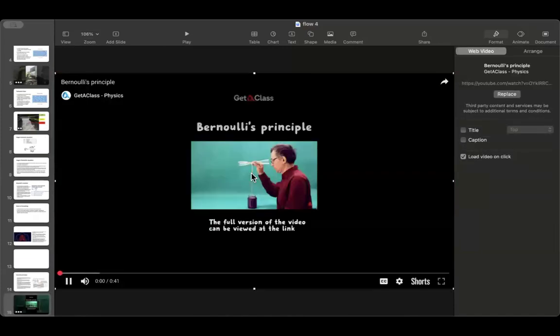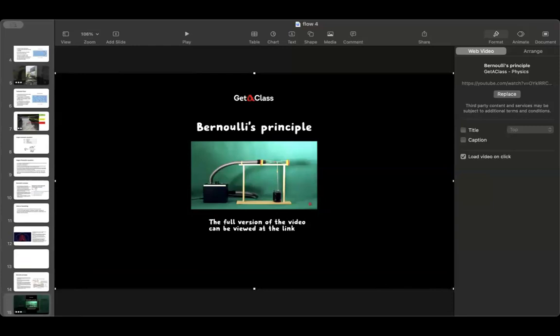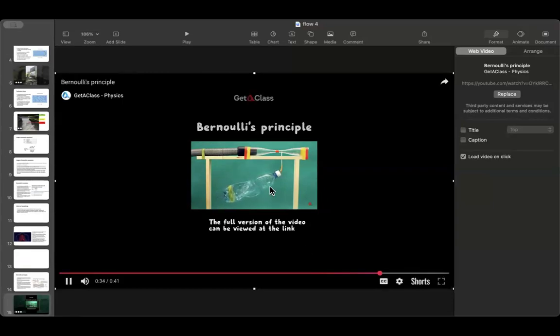This is a small video too. Let us put the lower end of the tube into the vessel with colored water and blow the pipe again. We can see that the water makes a 30-centimeter rise. We'll connect the pipe to the blower, which provides a far higher speed of airflow. We switch on the blower, and what we get is a perfect water sprayer. Now let us attach a plastic bottle to the pipe and switch on the blower again. That's incredible. A decrease in the internal pressure.